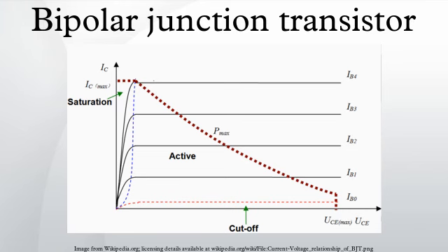Vulnerabilities: exposure of the transistor to ionizing radiation causes radiation damage. Radiation causes a buildup of defects in the base region that act as recombination centers. The resulting reduction in minority carrier lifetime causes gradual loss of gain of the transistor. Power BJTs are subject to a failure mode called secondary breakdown, in which excessive current and normal imperfections in the silicon die cause portions of the silicon inside the device to become disproportionately hotter than the others.